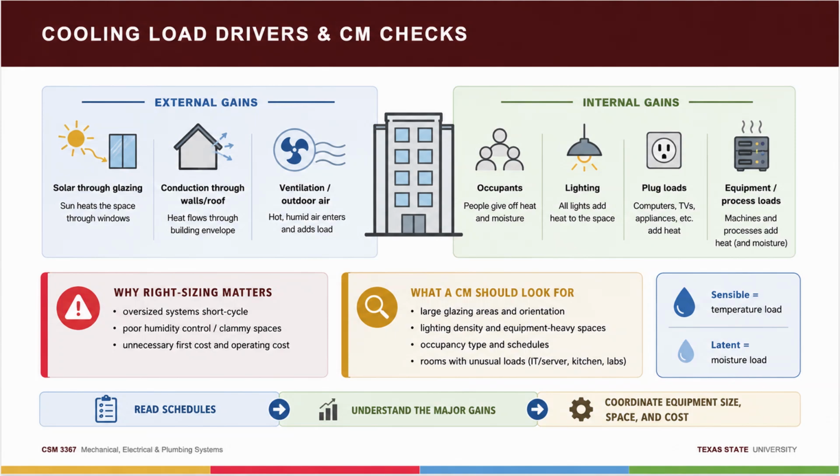Two, reading equipment schedules. Look at any mechanical schedule and you'll see the unit's total capacity and its sensible capacity listed separately, and their ratio, the sensible heat ratio, sensible over total. A unit with 60,000 BTUs per hour total and 45,000 sensible has a sensible heat ratio of 0.75, meaning a quarter of its muscle is budgeted for wringing out moisture. In a dry climate, you'd pick a high ratio unit. On the Gulf Coast, lower. Two 5-ton units are not interchangeable if their splits are different. And that's exactly the kind of thing that hides inside an or-equal submittal.